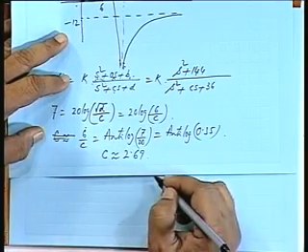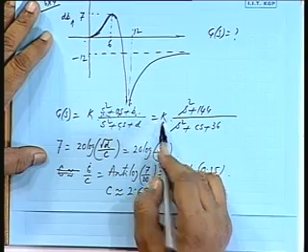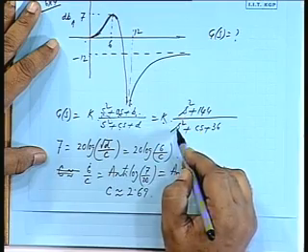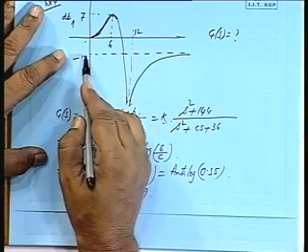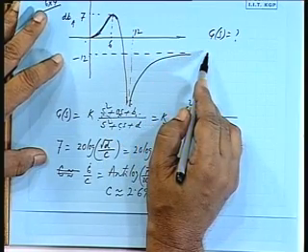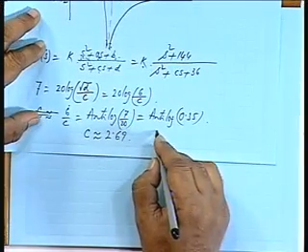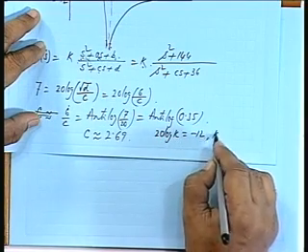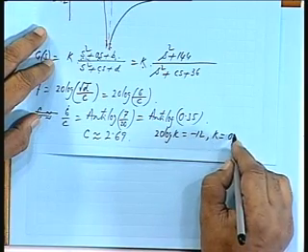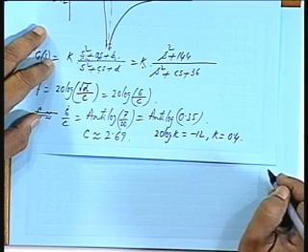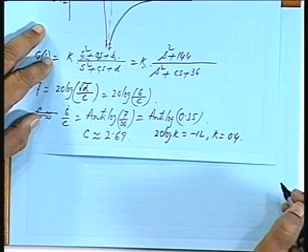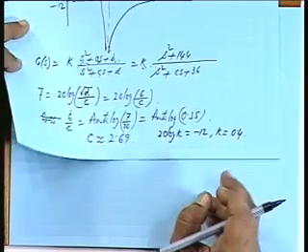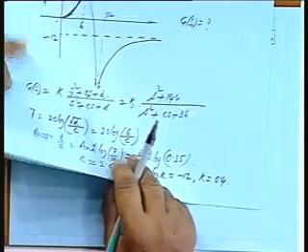So, once you know c, now what is to be calculated is k. When s tends to infinity, this will be 1, so 20 log of k is equal to minus 12, is it not? As s tends to infinity, 20 log of k is minus 12, so k is approximately 0.4. Is that all right? So, you know all the values.